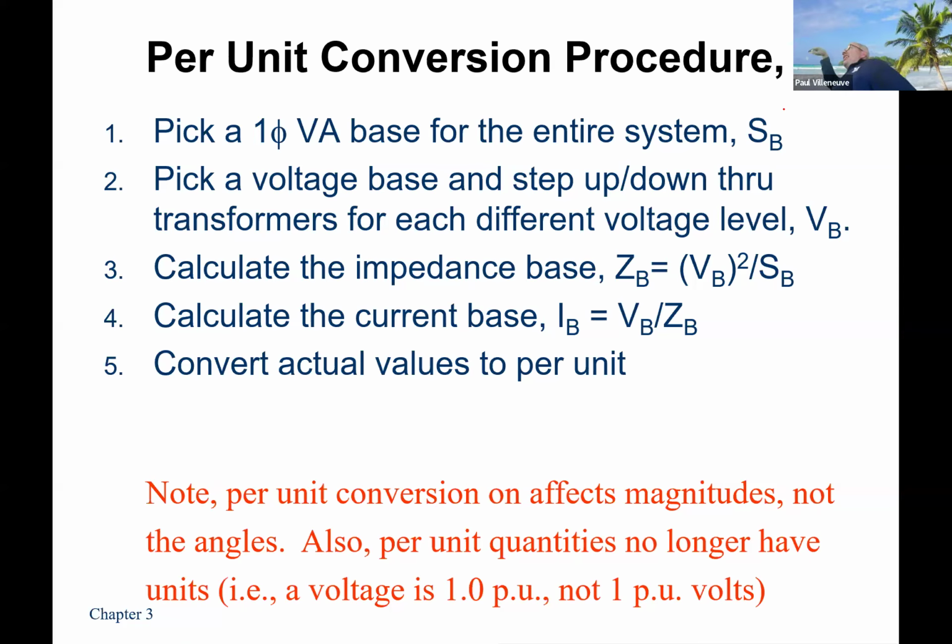Because your base has now changed from 100 kV to 20 kV, all right? So when you set up your systems, you can actually get rid of all the transformers, except for maybe the phase shift. So oftentimes when you represent a power system, when you're doing calculations, it's all just impedances and sources. There are no transformers anywhere in the diagram because I don't want to do the reflecting impedances back and forth.